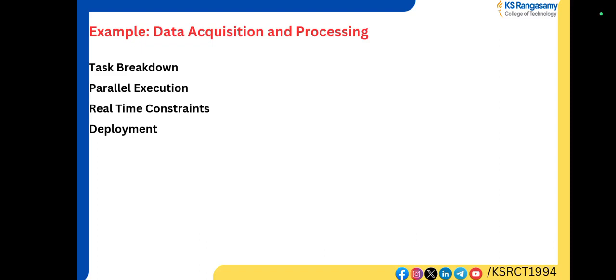so we have to assign high priority to data acquisition tasks to ensure timely data capturing, because the data capturing is the foremost task which gives information to upcoming tasks. So we have to assign high priority to data acquisition. Then we have to set appropriate priorities for processing the data as well as logging tasks based on the criticality. Then deployment, so we have to configure the project to run on real-time targets like CompactRIO, deploy and test the application to ensure it meets the real-time performance requirements.